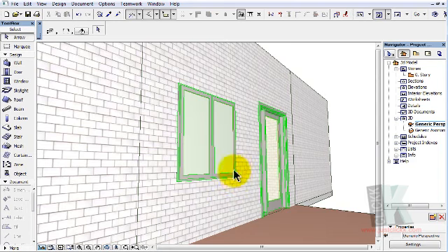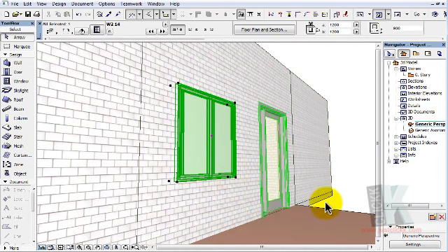So in addition to this, we didn't include the elevation of this window, as in the offset from the slab level. This window is assuming the offset from the ground level. It's not from the slab level. So that means the baseline of this should not be 900. This should be 1050. So 900 plus your 150 is what should be here. 1050.